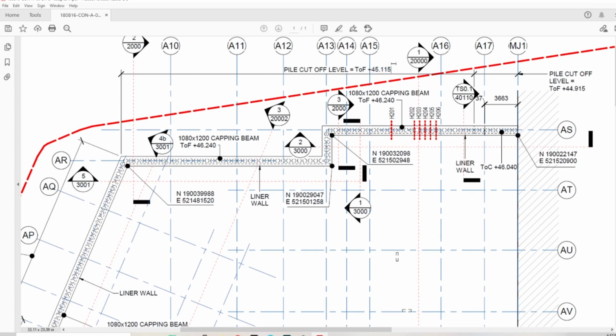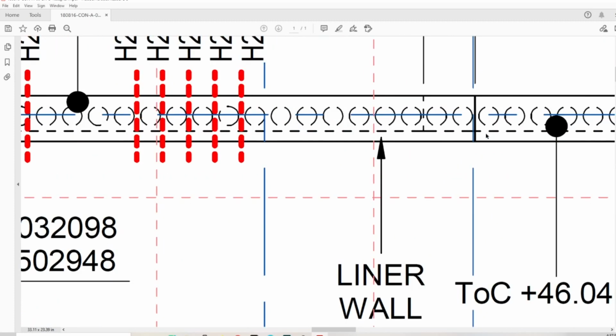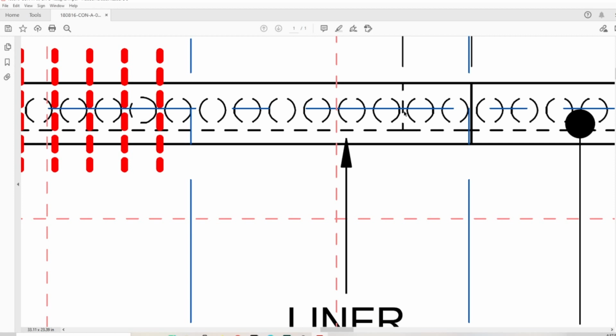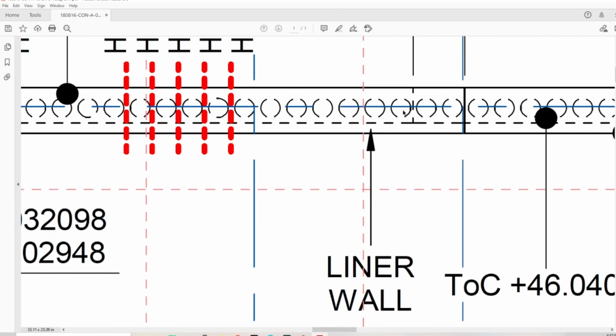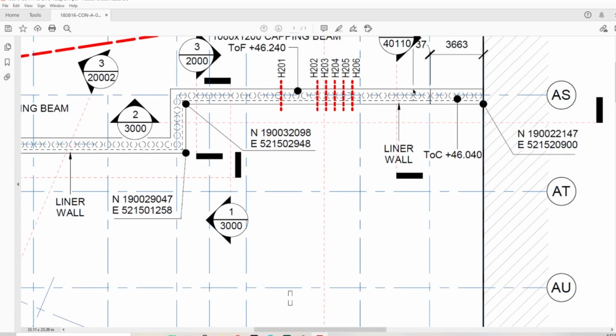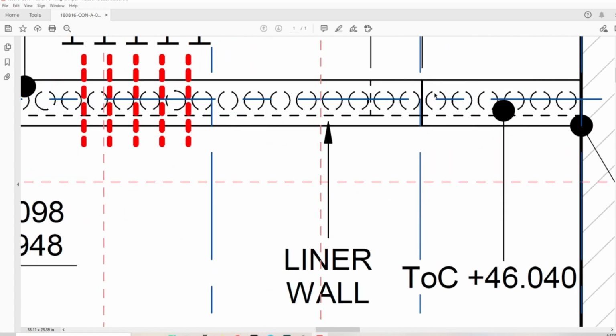So this is 85. Yeah, this is 200 difference here. So that's going to be, when you're cropping the piles, your step in the soffit. So these piles have to be cropped higher, and then you need to mark clearly for the guys that they're going to be steps. So I show this in my videos as well. I'll try to mark these things on the hoarding with big spray lines, so guys know they're going to be changed.